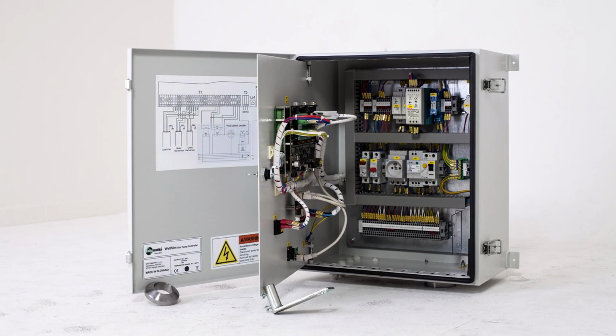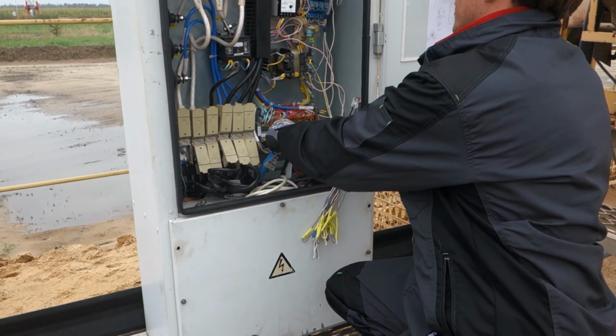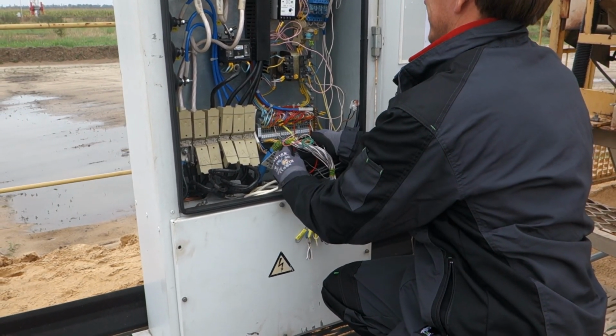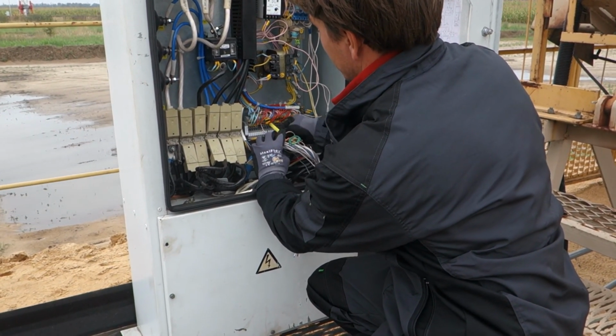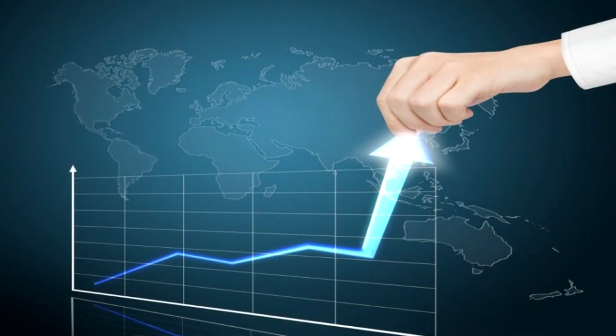The controller recognizes these and other patterns with an accuracy of 95 to 97% and also provides the user with the ability to use the recognized malfunctions as emergency set points that issue a warning to the dispatcher or stop the well. The use of advanced automation technologies requires time to get used to, but a glance at the numbers of the increase in the overhaul interval from the correct operation of the wells is enough to understand that it is worth it.